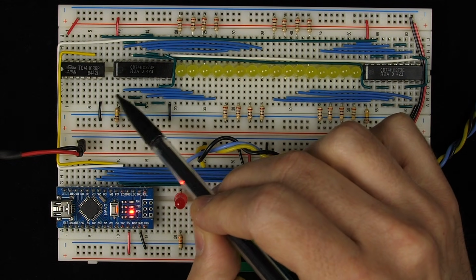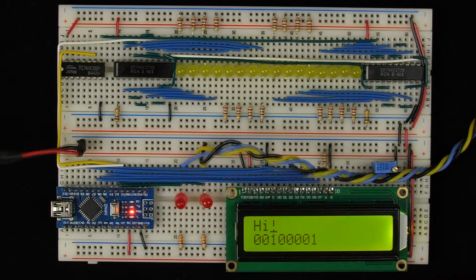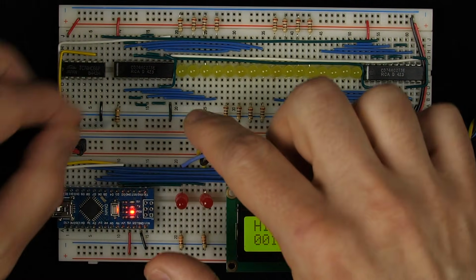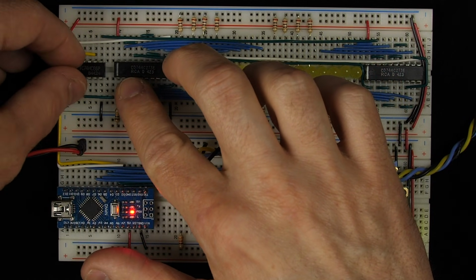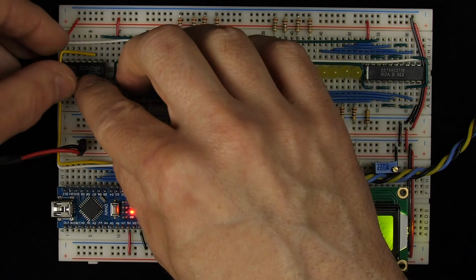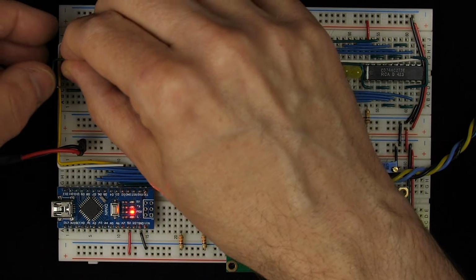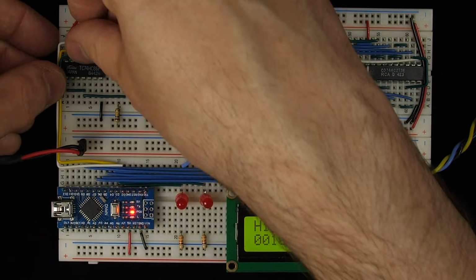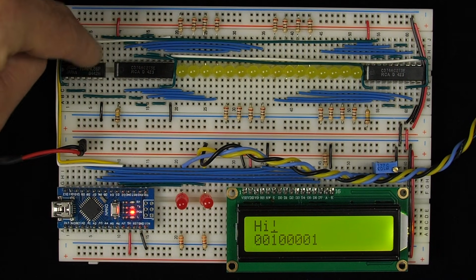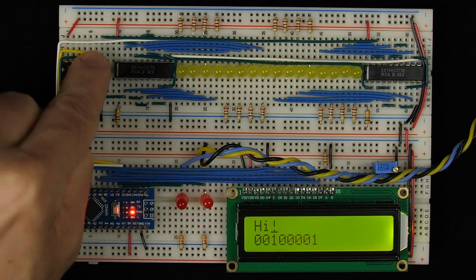So I'll just sort of chain it around, because we're going to need that same signal to go to all 3 of the XOR gates that we're using. So I'll connect pin 2 to one of the inputs for the first XOR gate down there, and then I'll continue that around to one of the inputs for another XOR gate, and then I can bring it around to the top to an input for that third XOR gate, which is the one at the top that we were using before. So now we have our data coming out, it's going into this XOR gate at the top.